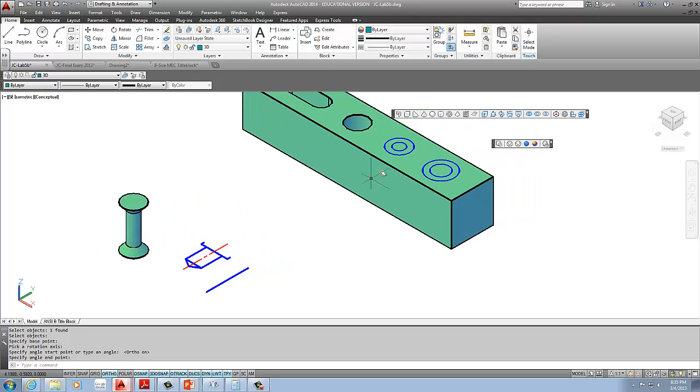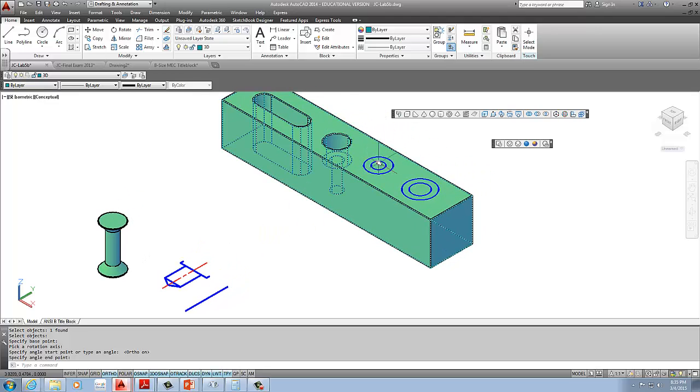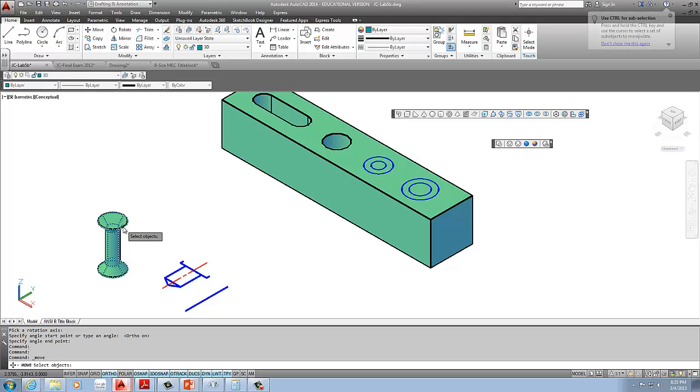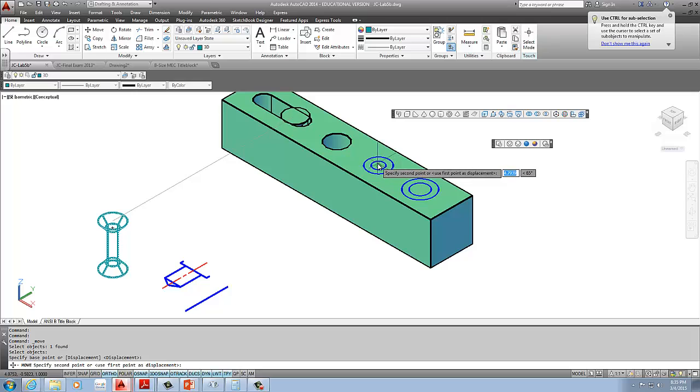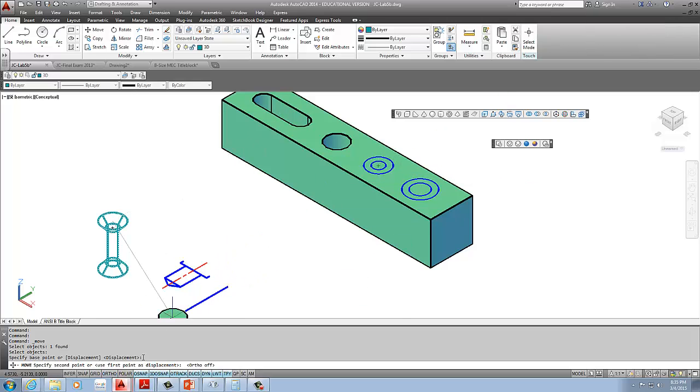To place it, this is the reason I brought this sketch geometry into the other object. It marks the location for that. This is two-dimensional geometry, and it's not going to interfere with the model. So I use it to mark the location for it. What I'll do is then I'll move this geometry from the center here to the center here, and my ortho's on.